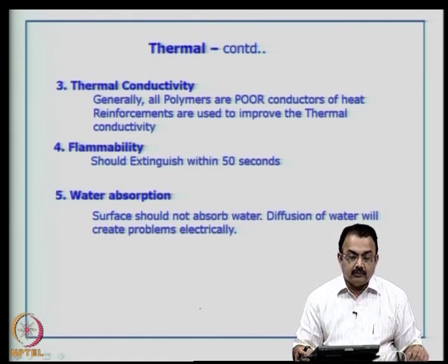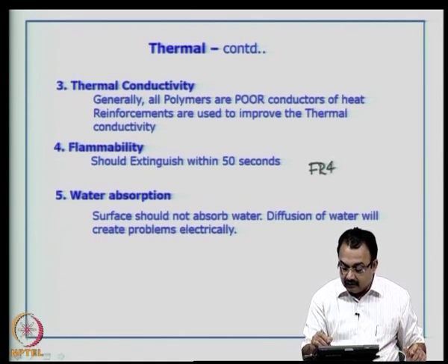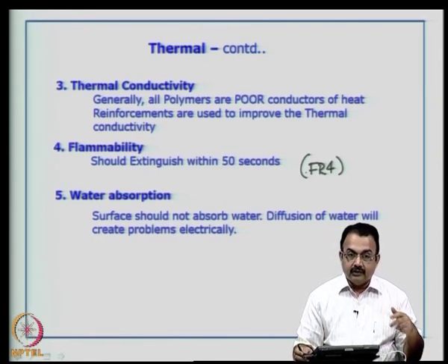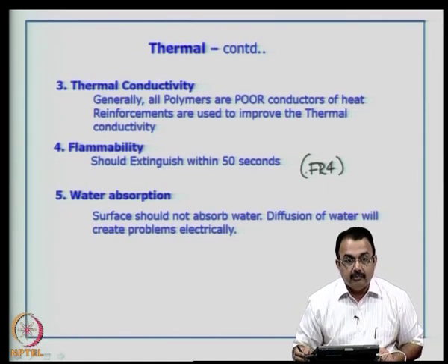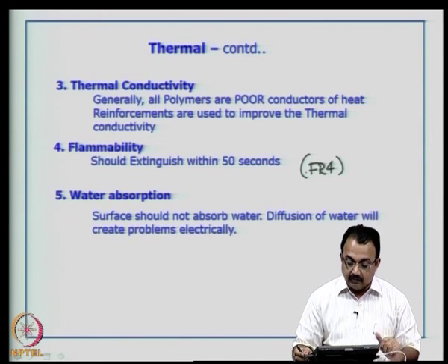Flammability should extinguish within 50 seconds. I was talking about this particular point when we talked about the classification FR4 and so on. So, certain tests are done to find out if it follows these flammability or the self extinguishing property for glass epoxy. Other materials are also available.